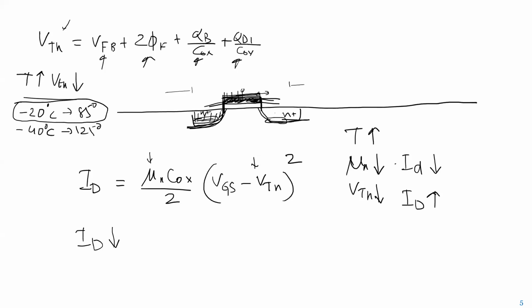And he immediately goes, oh, yeah, you have a linear potentiometer. Your ear hears in logarithm. That's why your sounds are increasing in log scale. That's why this is happening. I did not understand. I said, okay, whatever, give me a log pot. So he gave me a log potentiometer. I changed it and, beautiful, then it just changed very linearly.